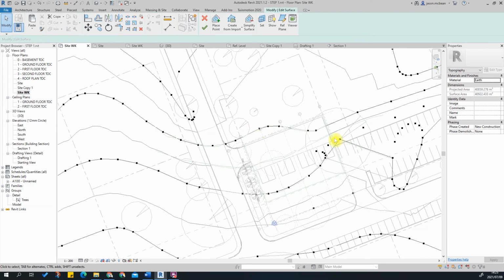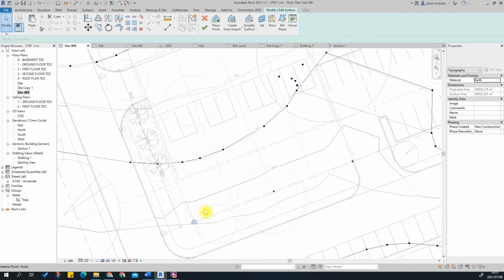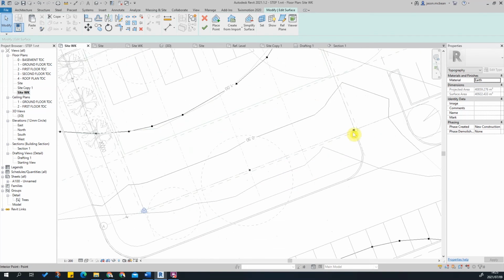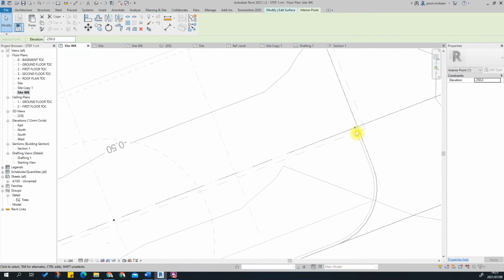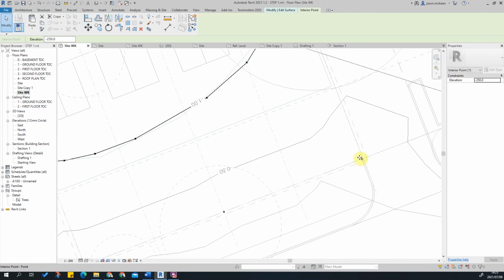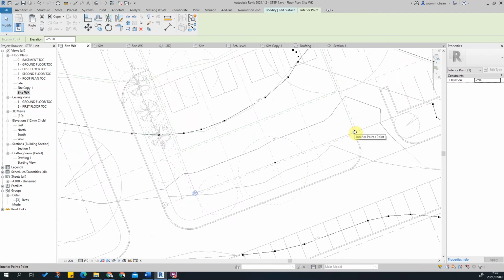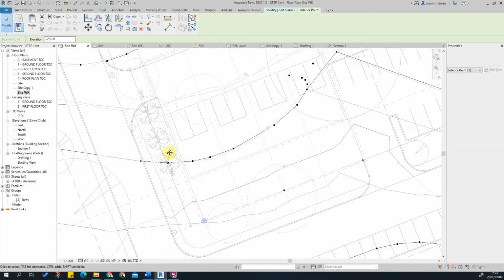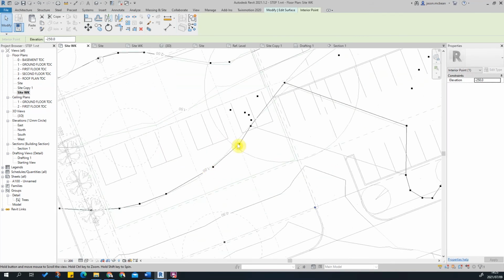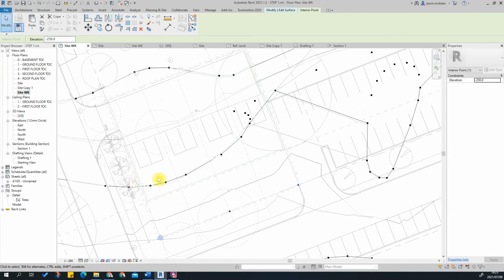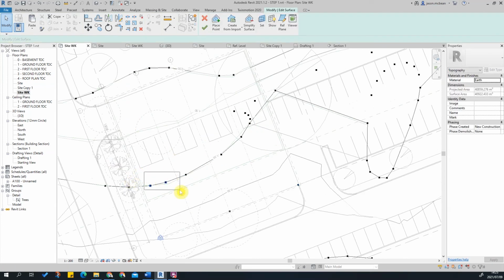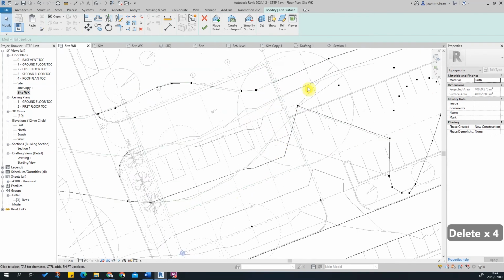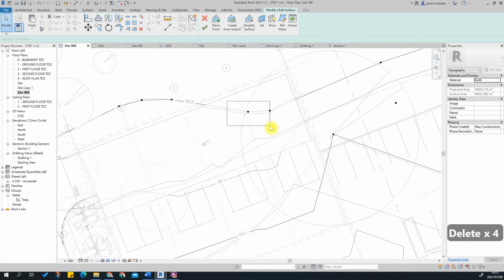Press OK. Now we know that this is our line of where our basement starts, and on that point there's going to be a difference here. There's going to be a step. So from there to there, there's going to be a slight step. Okay, so I'll leave these as they are, but I'm going to introduce some more points, and we might have to start introducing how these things will work. Okay, so here there's going to be no points for the minus 1.5 meter, and I'll show you where that's going to occur. I'll leave that just like that. And the -2 meters, it will now start following.